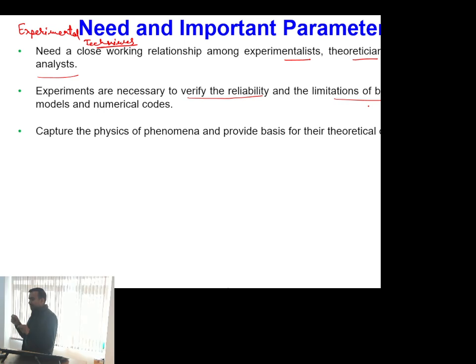Later on people have tried to enter into the minute details of the boiling phenomena, that is how bubble generation takes place at the nucleation site, then how that bubble grows in size, then how that bubble departs from the surface. So depending upon that understanding, they have developed the theoretical understanding.